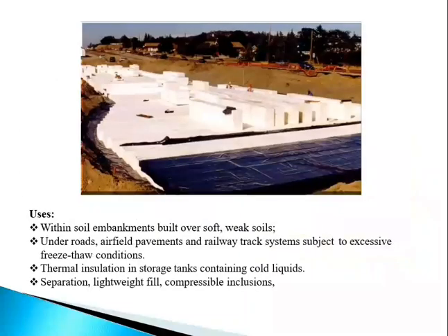So uses: with soil embankments built over soft or weak soil, under road, airfield pavements and railway track systems subjected to excessive freeze-thaw conditions, thermal insulation in storage tanks and containing cold liquids, separation, lightweight filling, compressible inclusions.